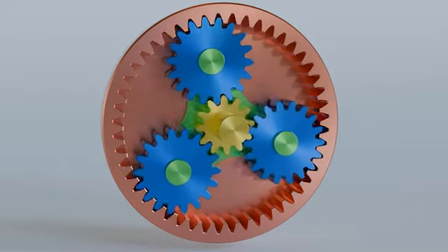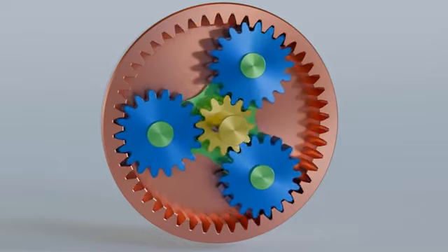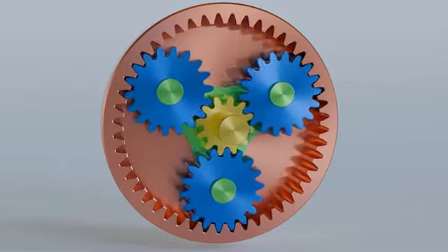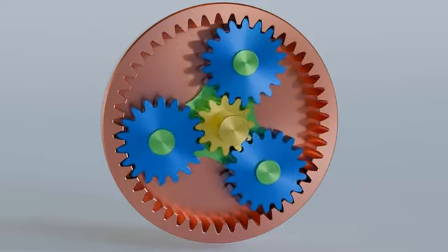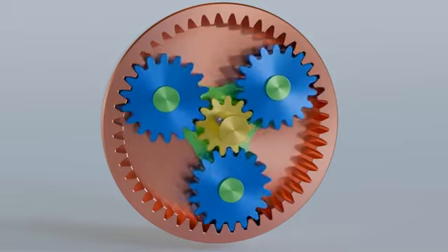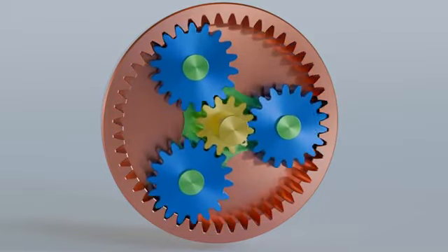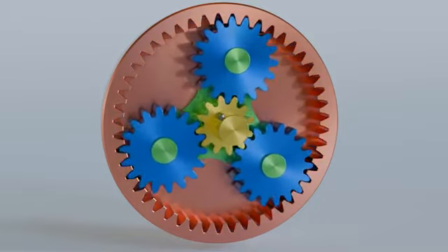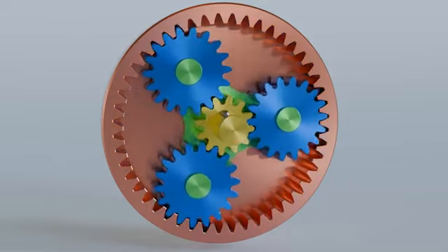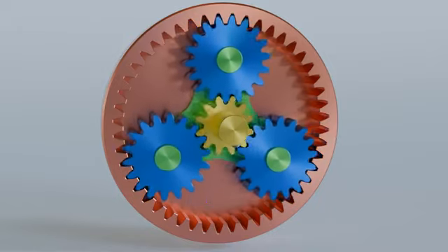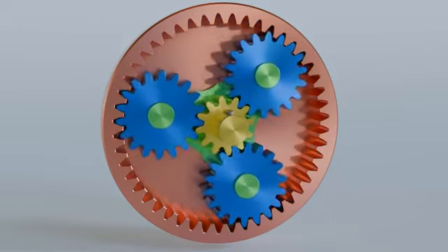occur at high speeds. With a planetary gear, it is not only possible to lock the ring gear and have the output take place using the carrier. There are many other possible variants, which we will go into in more detail in a moment, and which each result in a different transmission ratio. This makes the planetary gearbox particularly suitable for shiftable transmissions, such as in hub gears of bicycles or in automatic transmissions of motor vehicles.